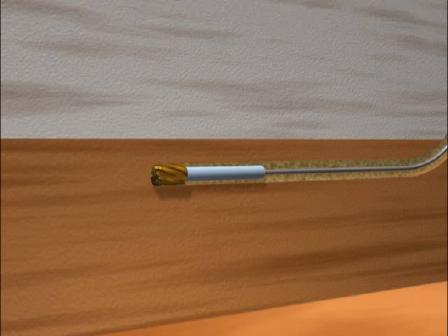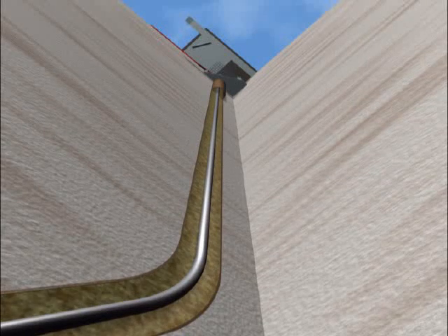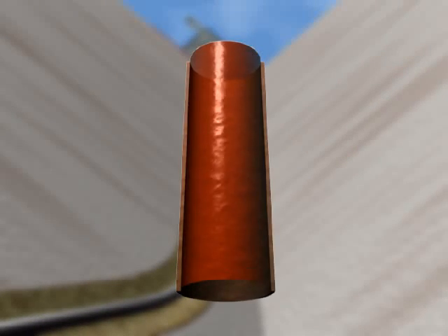Reservoir pressure and depth determine the required density of the drilling fluid system. Unlike conventional drilling, which is limited to simple fluid systems, underbalanced drilling uses a variety of fluids to control bottom hole pressure. At the high end of the density scale, light fluids such as water, synthetic base oil, natural crude or diesel form the drilling fluid.